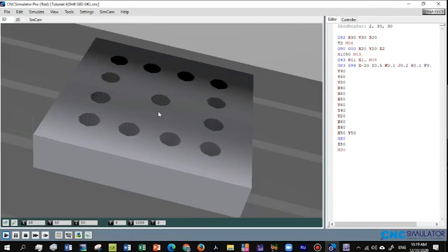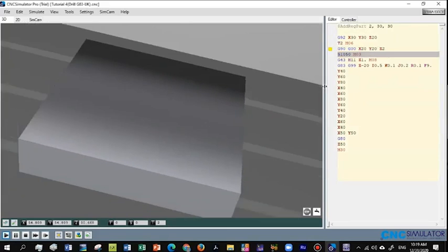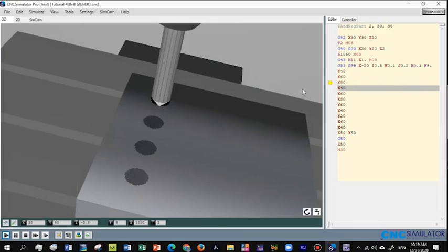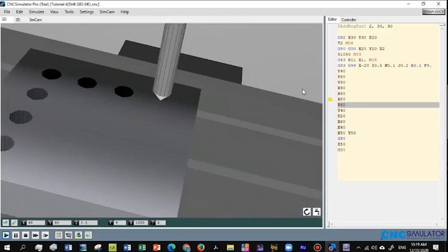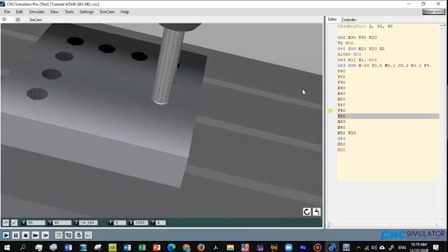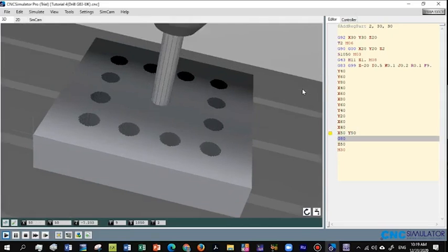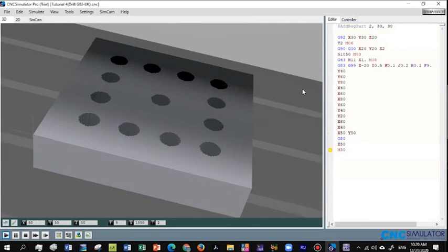So when the drill is used to make a hole with more than one stage, it can use the G83 with these stages. Here, the thickness of the workpiece is small, and the maximum it can go is 30 millimeters only. In all cases, we just need to define one model code with its required parameters.